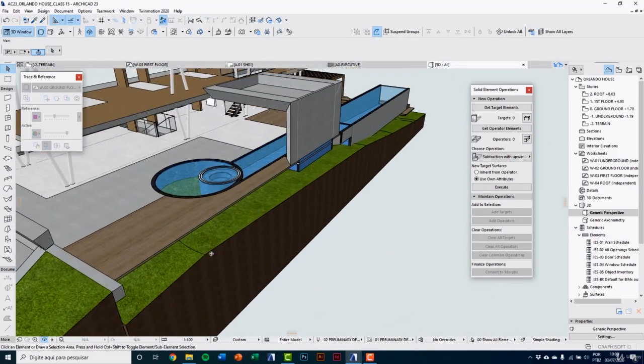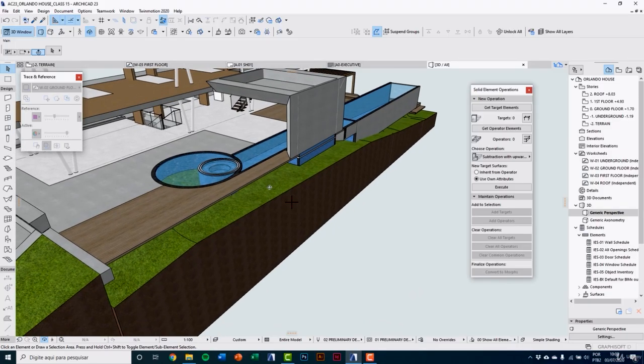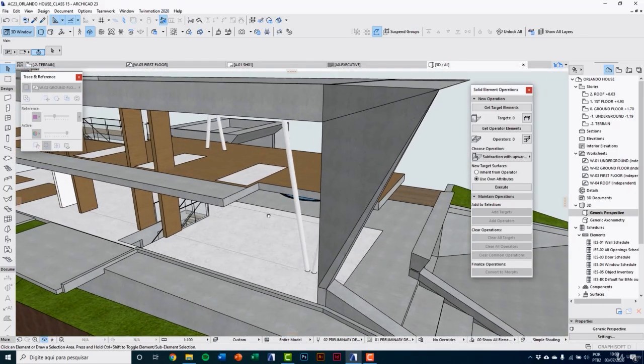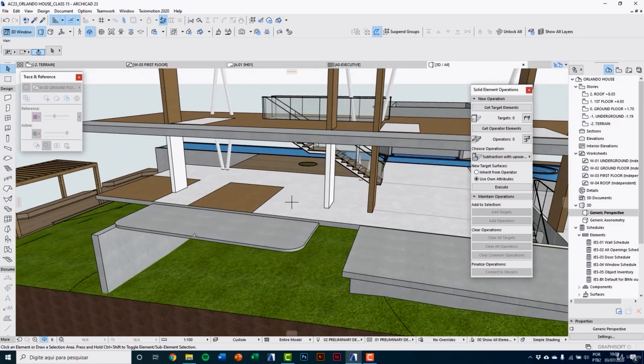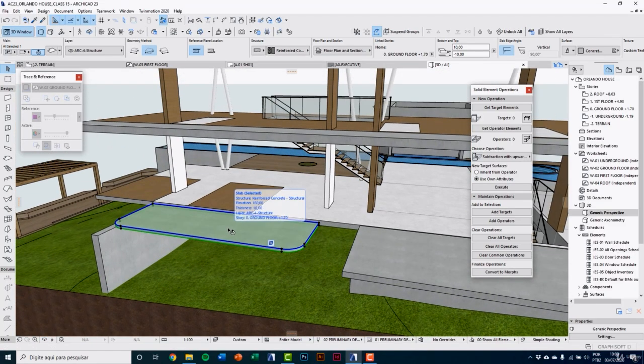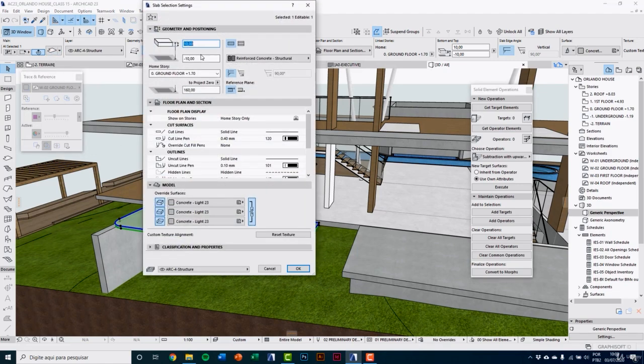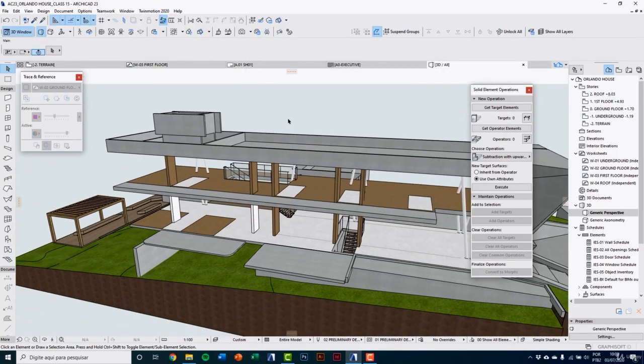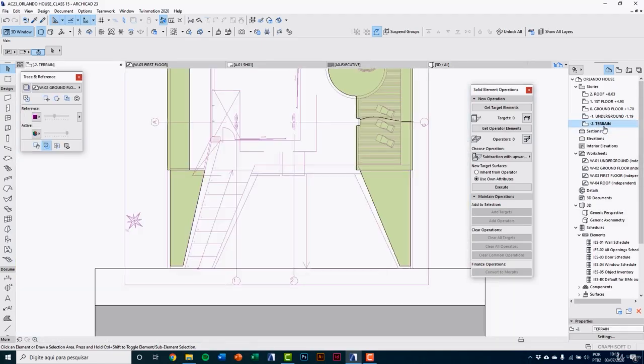Now we're going to do this grassed plain area, and to do it, we'll elevate our points to the same level. So, come here to this outer surface area, selecting the concrete slab. I see the level to home story is -10, and to project 0 is 160. Therefore, I will elevate all mesh points to 160 level. Go to Terrain. I can even turn off the reference to see it better.